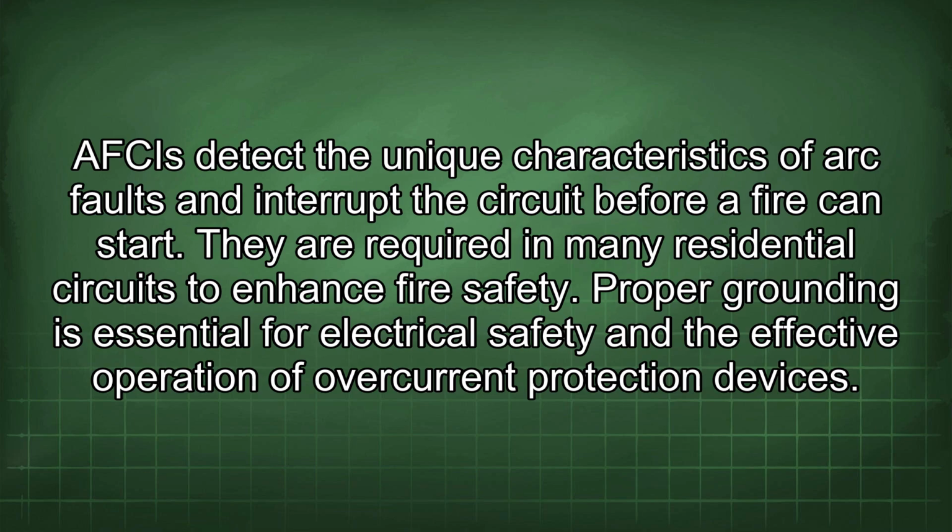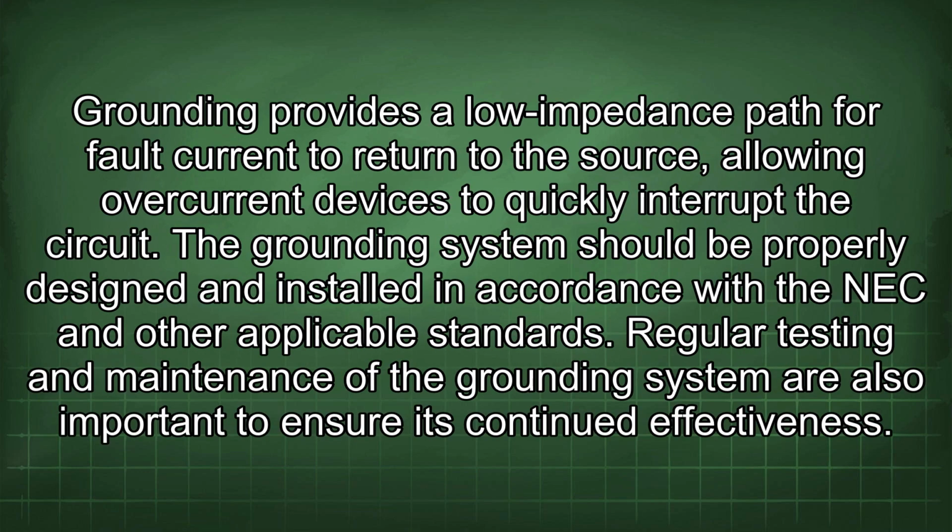Proper grounding is essential for electrical safety and the effective operation of overcurrent protection devices. Grounding provides a low impedance path for fault current to return to the source, allowing overcurrent devices to quickly interrupt the circuit. The grounding system should be properly designed and installed in accordance with the NEC and other applicable standards. Regular testing and maintenance of the grounding system are also important to ensure its continued effectiveness.